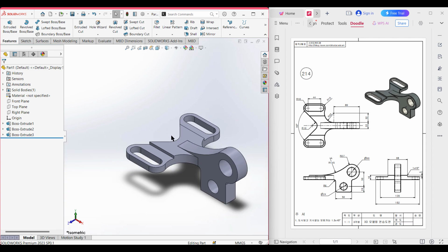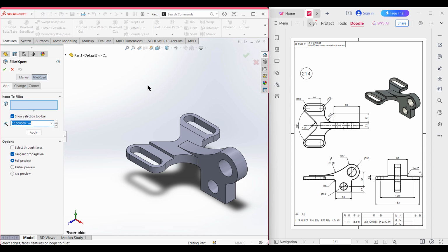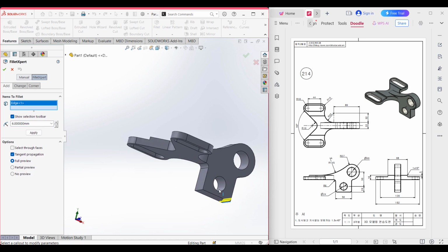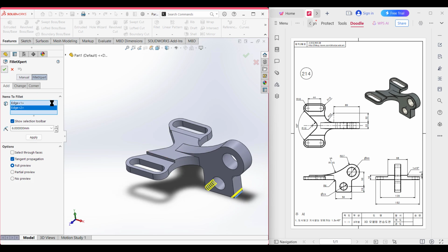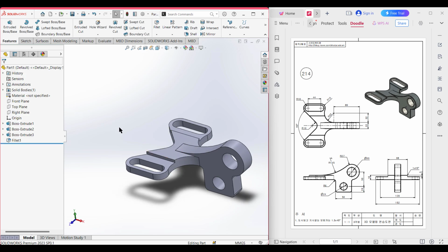Now it's time for some fillet or chamfer. We have the same fillet here also. So I'll give it a fillet of 6 radius here, also in the same way. So I'm selecting the fillet from here and a 6 unit fillet for this portion, and rotate it again, and give the same fillet on this side. Now press OK. Now isometric it again.